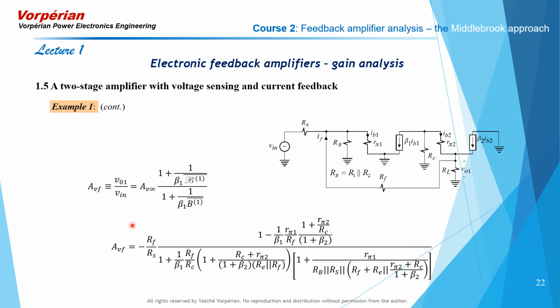And you don't have to stress over determining the G block and the H block of the feedback block diagram and trying to force this amplifier into that block diagram in order to be able to determine the closed loop gain AVF. As I said, it all comes out naturally out of the feedback formula given by the extra element theorem for the amplifying element inside the forward path of the signal.